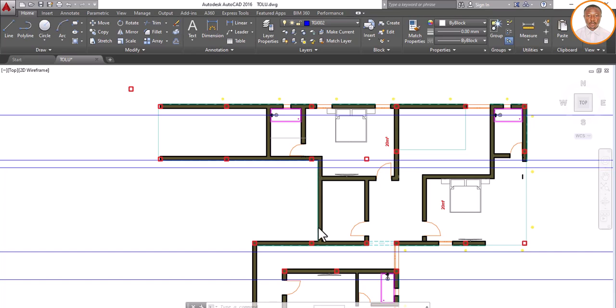At the same time, if you don't roof it, then there will be a problem with your slab here, because when it's raining, it's always going to be wet, which is not good for this wall here. Is that clear? So these are the things as a structural engineer you need to look properly into.